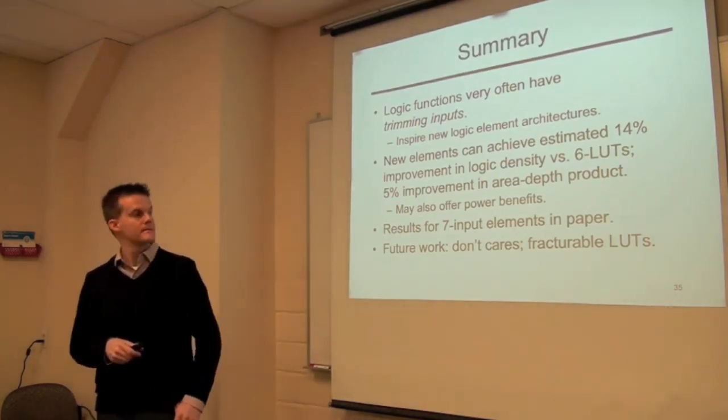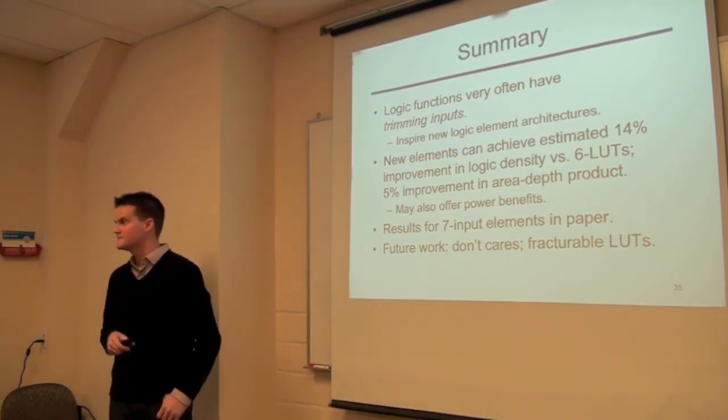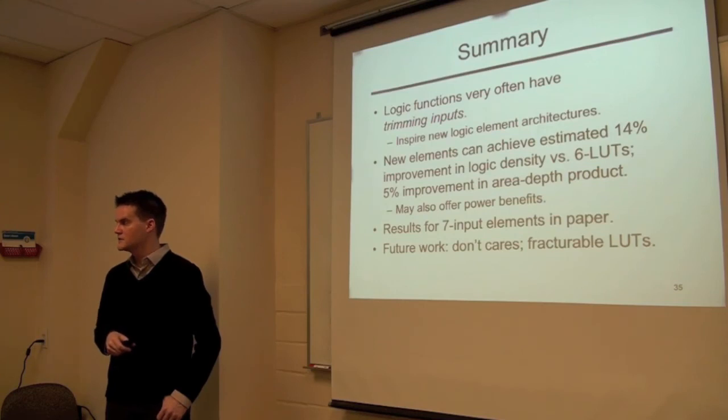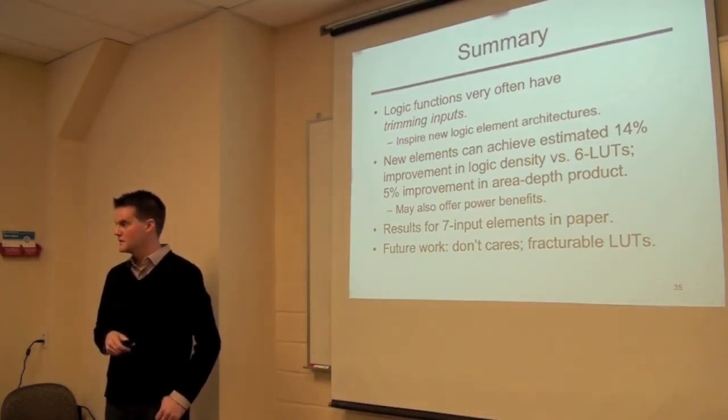One of the comments: I think the fracturable LUT future work is interesting and pretty important, because I suspect fracturable LUTs are intended to capture some of that unused circuitry, right? There's a big mux tree and all these SRAM cells, and a lot of the time you don't find a big enough LUT, and therefore you won't use them. Well, I'm actually removing the unused circuitry instead.